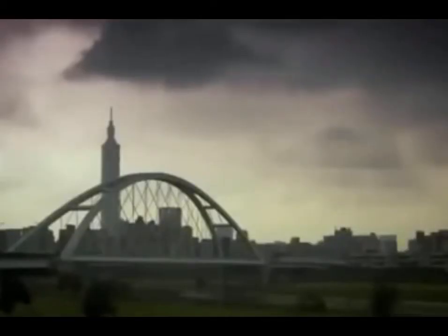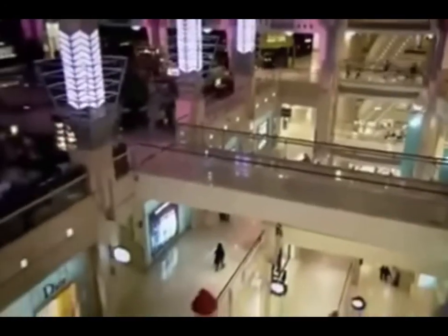As it begins to swing, the giant oil-filled cylinders take up the energy from 500 tons of swinging steel. This extraordinary footage, filmed on a cell phone, reveals the ball damping 545,000 tons of skyscraper as she sways in the typhoon. After 3 hours, the winds abate, leaving Taipei 101 to face another day.